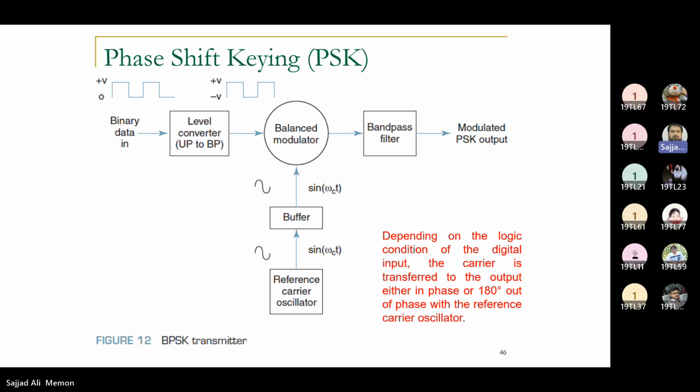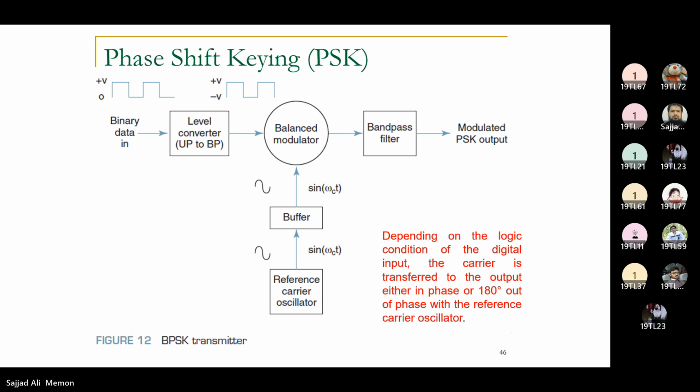Then we have the balanced modulator, where we have the carrier oscillator, the reference carrier oscillator, that is sin omega ct in this case. That will be multiplied with positive voltage or negative voltage.